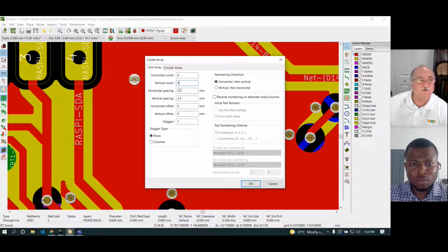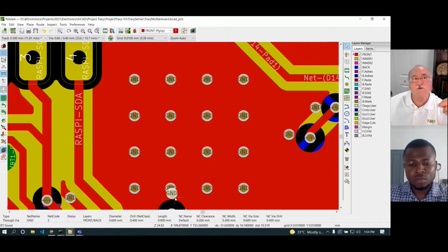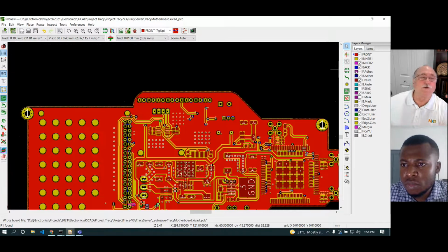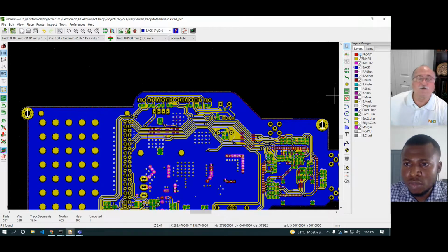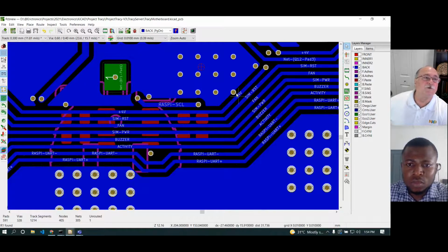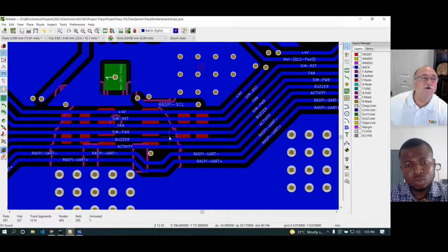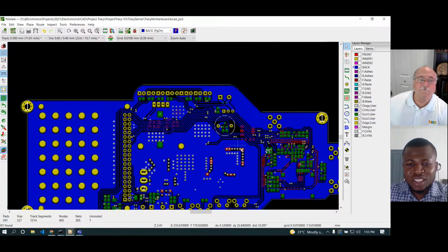So if you have a very fast switching event, that's where you need to consider having more space between the traces in order to reduce the impact of that. And that's why if you look at most of the memories, very high speed signals are not 5 volts anymore. They're 1 volt or 1.5 volts, because you're reducing the magnitude of that switching energy, and that reduces the crosstalk. That's the result of the creation of the magnetic field in the adjacent conductors. Okay. Very simple stuff.